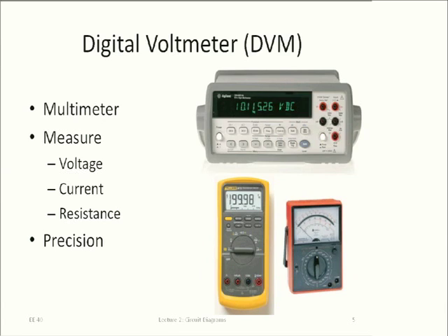What do they measure? Well, they're called digital voltmeters, and that's really what they are inside. But then just sort of on the shell of the digital voltmeter, if you add a little bit of extra circuitry, you can make it just measure current and resistance, and especially the cheaper ones, they will also measure capacitance and all sorts of things. Most of the time they will invent a number, and sometimes that number may even have to do with the actual value. But the main things you can measure is the voltage, current, and resistance. And if you want to measure other components, usually you'll use different instruments.